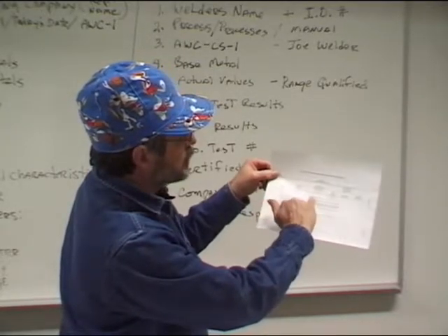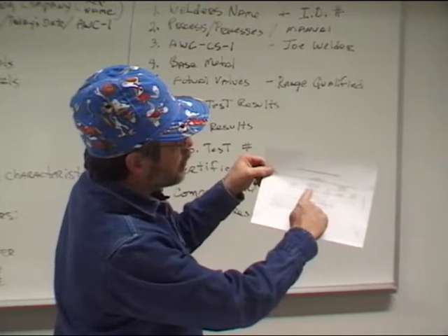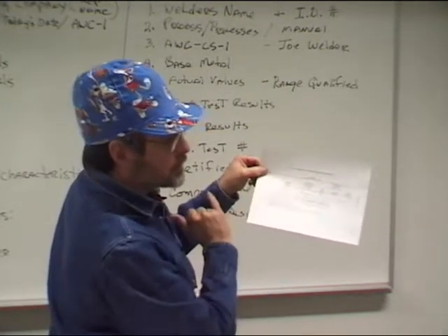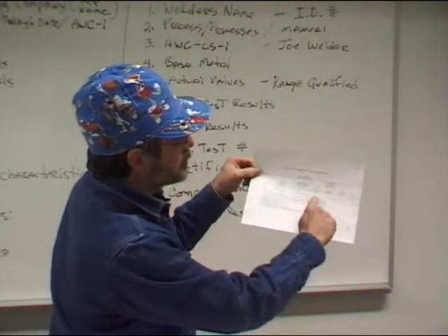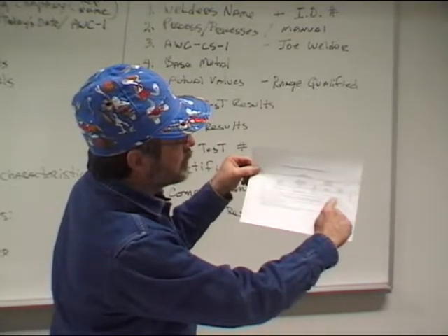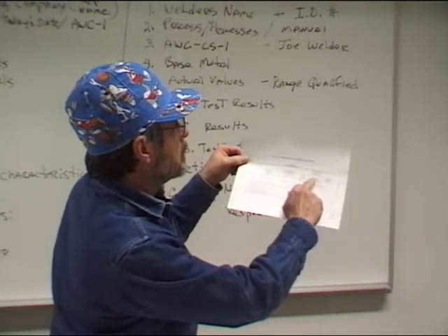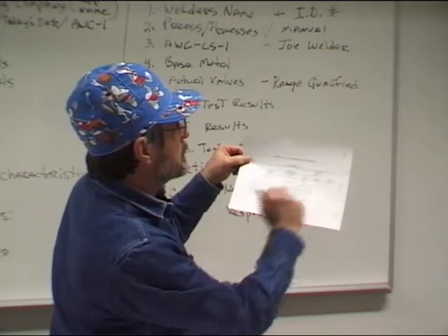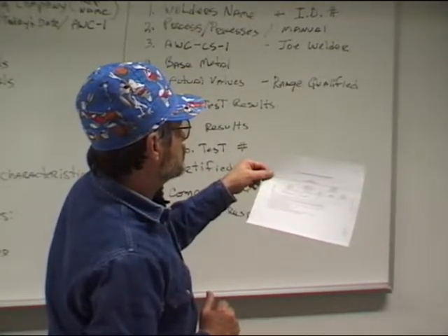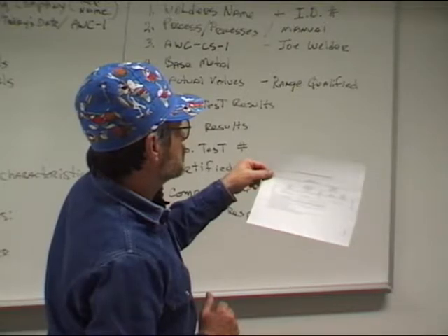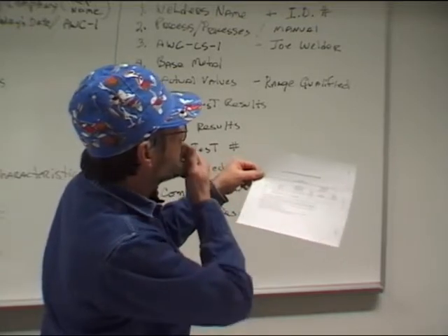So if you come over here, it shows that under the thickness T of deposited weld metal qualified, it says 2T. So they're qualified for twice the thickness. We've already talked about that. And then you come over here and it says, see these notes, and it says face bend 1, root bend 1. So it says type and number of tests required, and they would have to take these. And we'll give them two. We give them 2 bend tests. Okay, these are transverse bend tests.